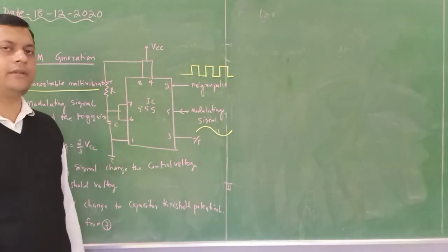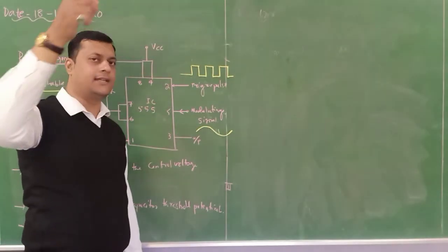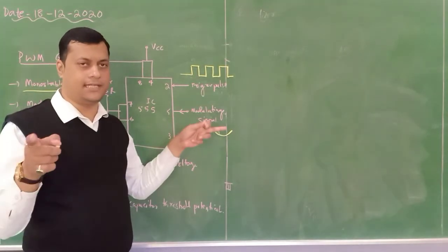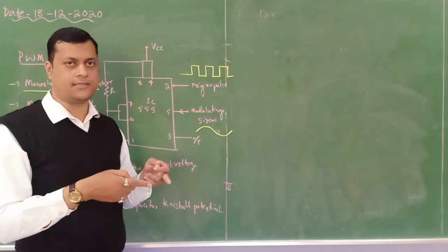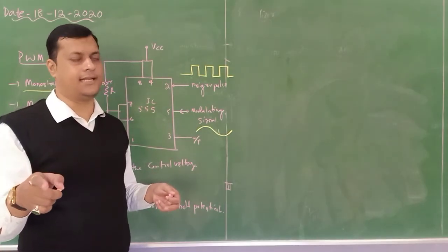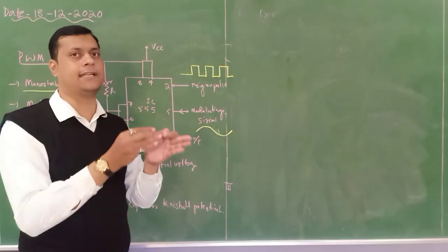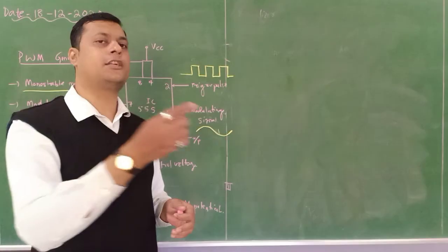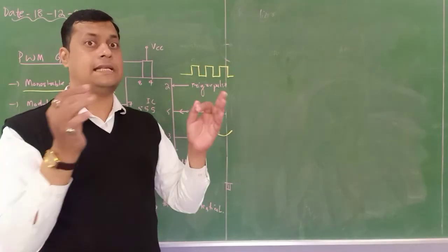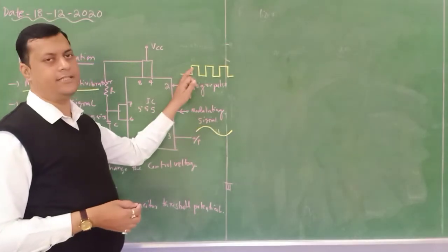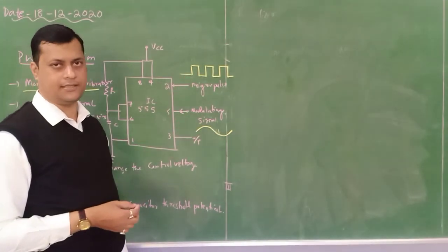In the previous figure we have seen, if the modulating signal increases, the width of the pulse is going to change. It will increase, and the frequency component reduces. Similarly, when the amplitude of the modulating signal decreases, the width of the pulses decreases, either with respect to the leading edge, the trailing edge, or the center. Now this modulating signal governs this particular triggering pulse.